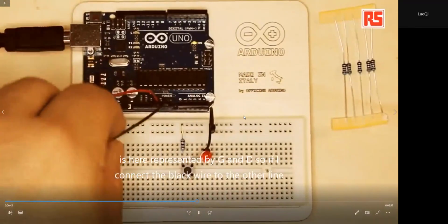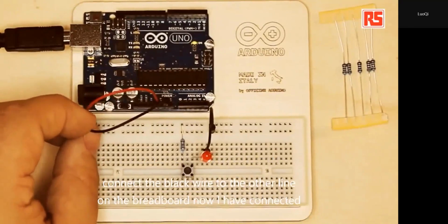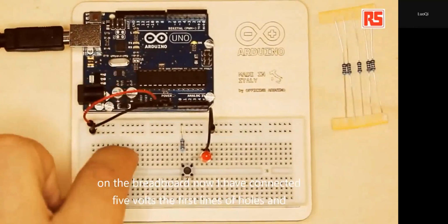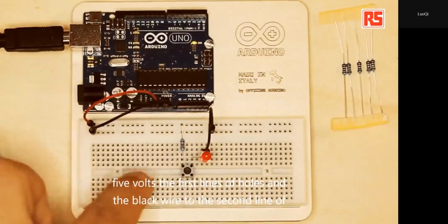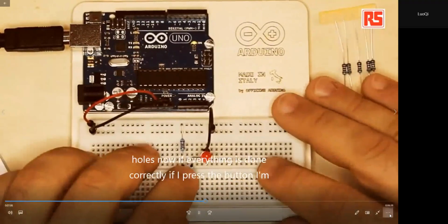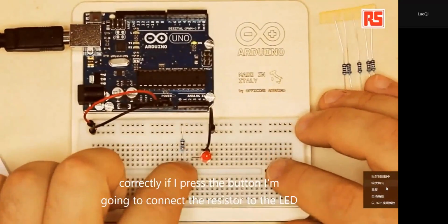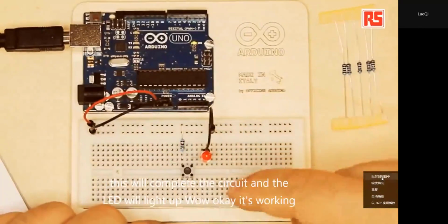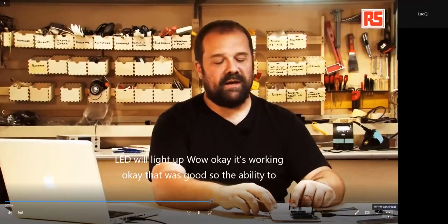So I connect the black wire to the other line on the breadboard. Now I have connected 5 volts to the first line of holes and the black wire to the second line of holes. Now, if everything is done correctly, if I press the button, I'm going to connect the resistor to the LED. This will complete the circuit and the LED will light up. Wow, okay, it's working. Okay, that was good.